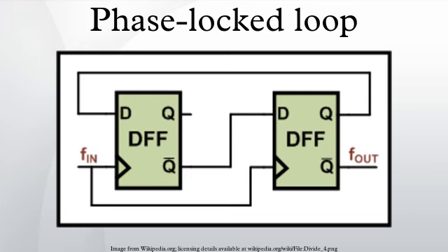However, if there is an accident, a pace car comes out to set a safe speed. None of the race cars are permitted to pass the pace car, but each of the race cars wants to stay as close to the pace car as it can. While it is on the track, the pace car is a reference, and the race cars become phase-lock loops. Each driver will measure the phase difference between him and the pace car. If the driver is far away, he will increase his engine speed to close the gap. If he's too close to the pace car, he will slow down. The result is all the race cars lock onto the phase of the pace car. The cars travel around the track in a tight group that is a small fraction of a lap.